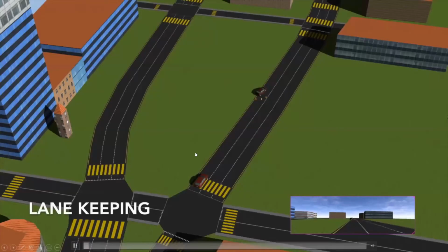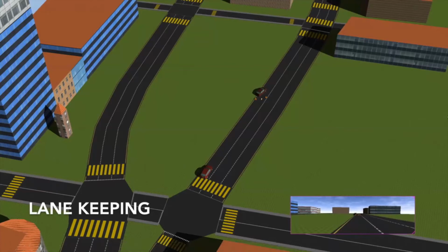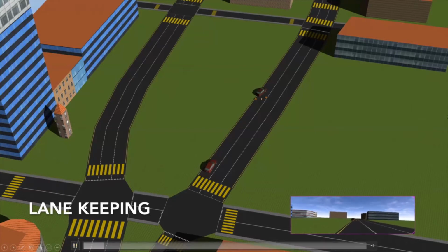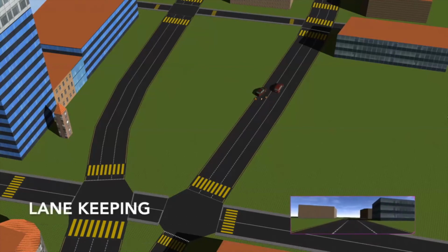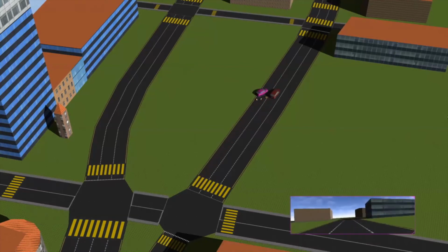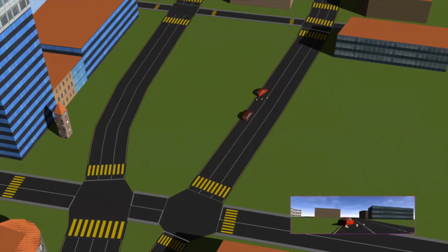Okay. So now what we're going to see is a simulation, a video showing the falsification in action, where, as you'll recognize, initially in falsification, you start out, you sample a point and you simulate it and you monitor the property, and you typically start with a safe or a correct simulation. And then using numerical optimization, we'll iteratively go towards behaviors that are unsafe or counterexamples. So the first simulation there was a correct maneuver. And now you're going to see more and more simulations where the ego vehicle gets closer. And in fact, in this case, it shaves a cone.